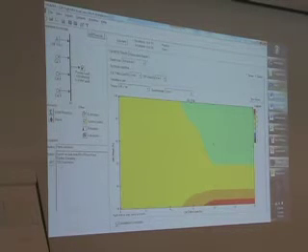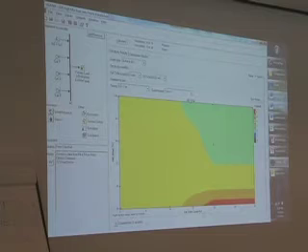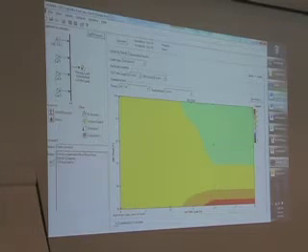So earlier, this was the file I was looking for when I said that I had a good example of how the operating reserve interacts with the minimum load on the diesel. What this graph is showing is the optimum number of wind turbines as a function of the operating reserve requirement and the minimum load requirement. If you allow the diesel to run at very low loads, the operating reserve doesn't matter much, so it doesn't affect the optimum number of wind turbines, which is 4.